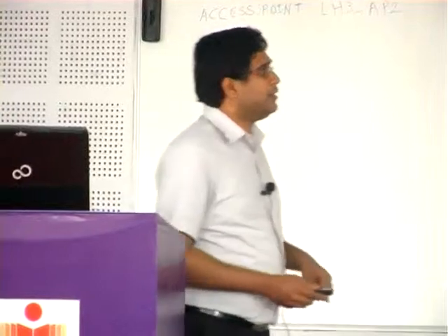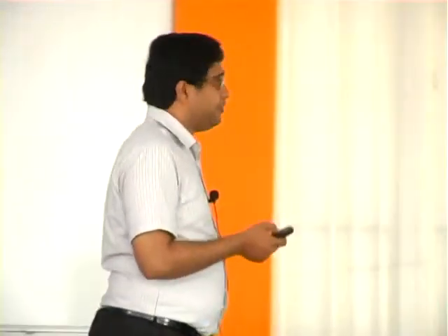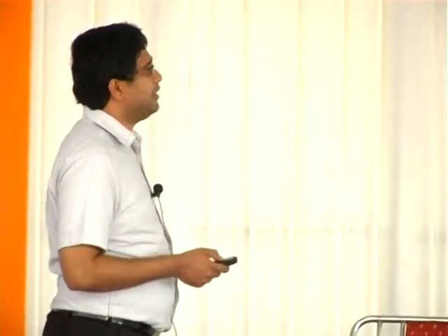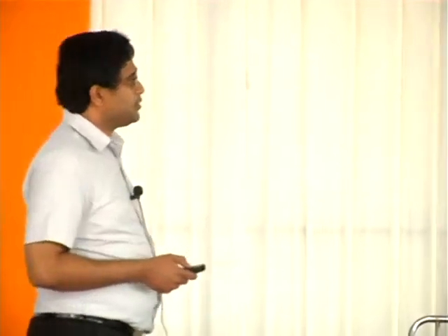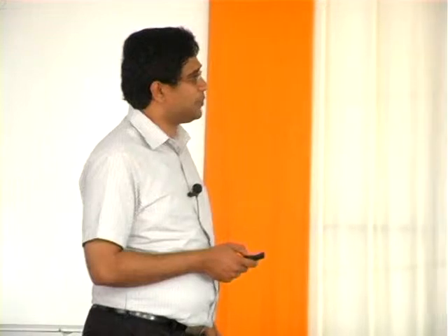So let's take a simple step of opening the windows for source and drain by protecting the other windows. What we need to do is take a silicon wafer, and you have a protective layer on top. So how do I get this protective layer? We can either do oxidation or low pressure chemical vapor deposition or plasma enhanced deposition. And this is the instrument that we use for that particular purpose. We have this even smaller instrument. After that, you actually do a spin coating.